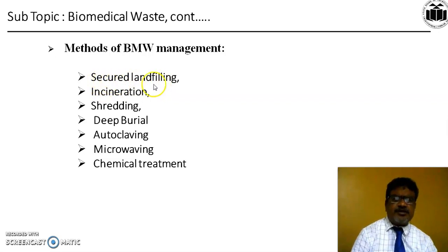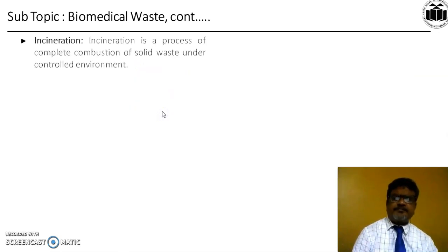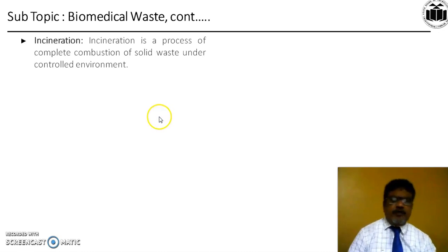Therefore, it is called as secured landfill because biomedical waste is most hazardous waste, and therefore, to prevent the contamination of biomedical waste into the water sources, the two liners are provided, and therefore, this landfilling is called as secured landfilling. Now we have to see other method of management of biomedical waste, that is incineration.